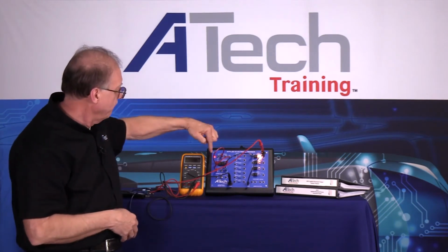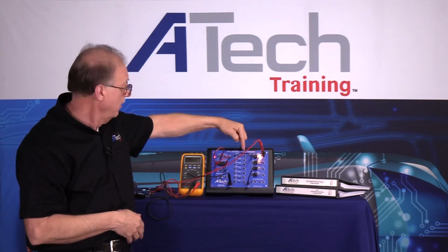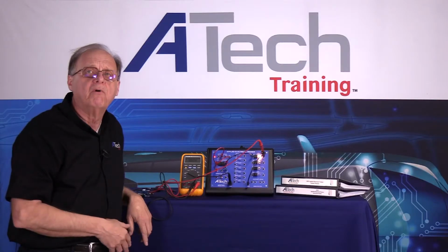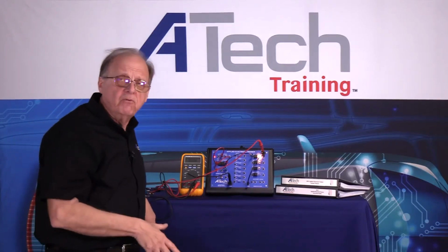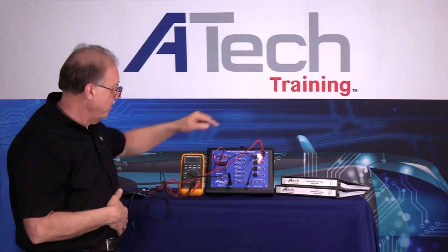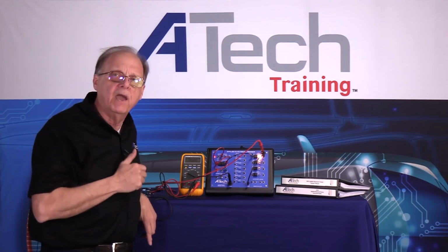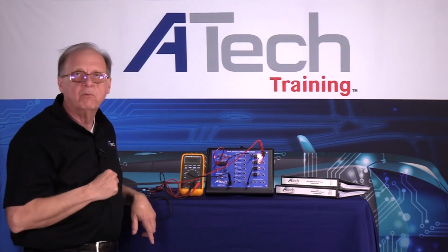What it tells me right now is I have a good series circuit. It means that I have had a little bit of voltage drop coming over there, but at this point, if my device and my load's here, it should use all the voltage. If the load doesn't use all the voltage, we have an issue, or I have a bad ground. When I got a good ground here, if I wasn't doing the work, that would indicate a bad load device. So that's one thing we can look at.